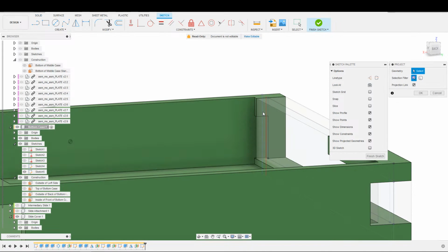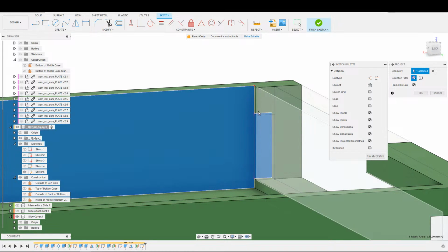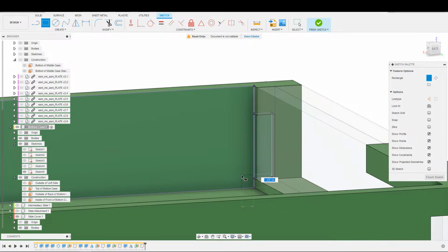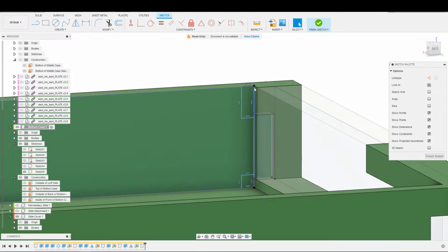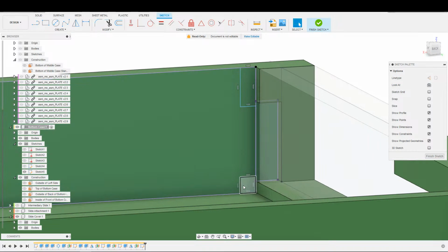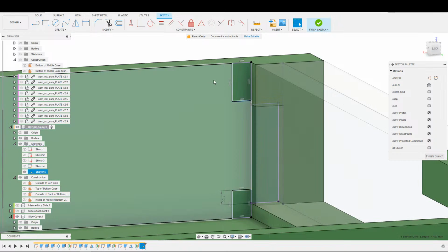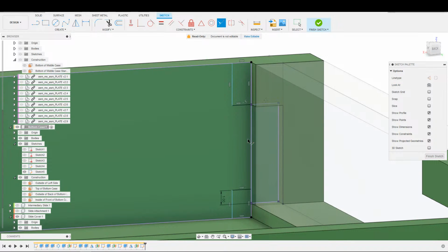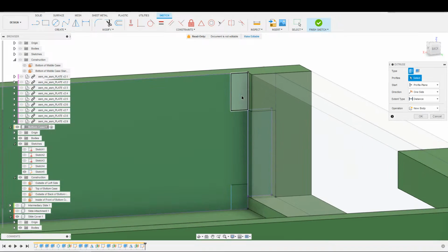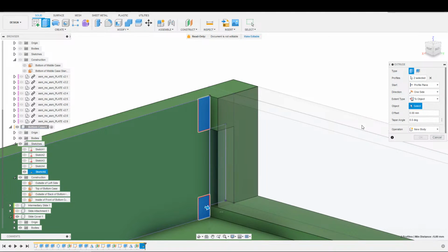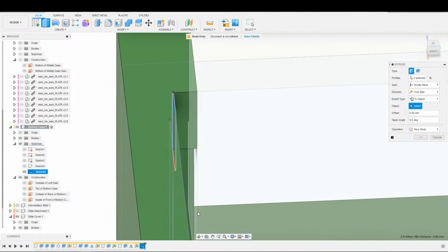And I'm going to instead do the top and the bottom at the same time. And extrude them out in this direction so that I can do it at the same time. And I will go ahead and drop this all the way down just because we already have that there. So again, this is just going to be 1 millimeter here. And this guy actually can be, you know, up here in line with this because the bolt isn't going to run into it one way or another. So we go ahead and extrude this out. And again, it only has to be to that object plus a little bit to make sure it hits.